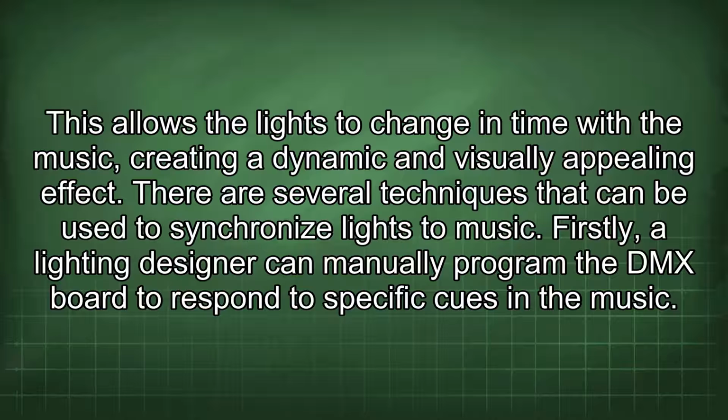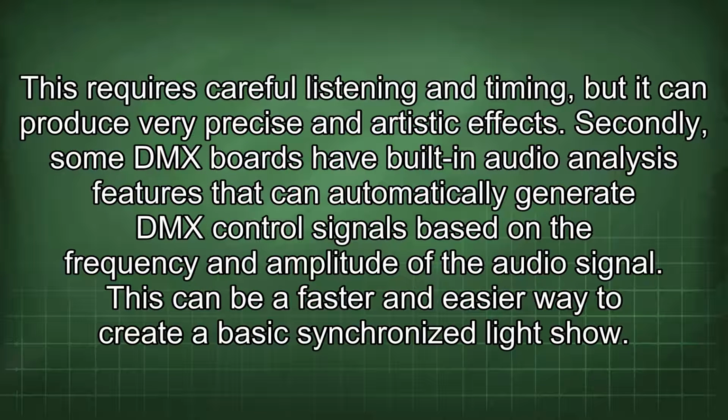Firstly, a lighting designer can manually program the DMX board to respond to specific cues in the music. This requires careful listening and timing, but it can produce very precise and artistic effects. Secondly, some DMX boards have built-in audio analysis features that can automatically generate DMX control signals based on the frequency and amplitude of the audio signal. This can be a faster and easier way to create a basic synchronized light show.